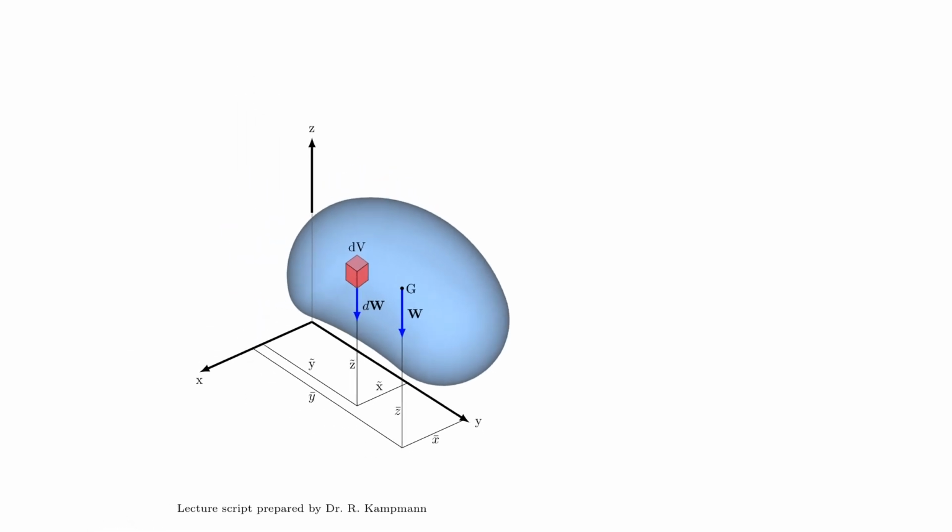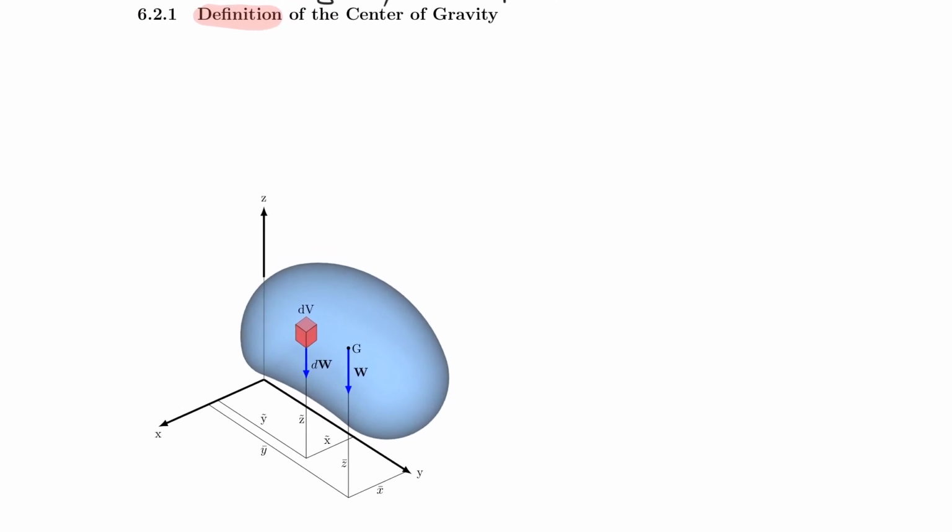So now the way the center of gravity is defined is that whatever point in space you choose, let's say you choose the origin of the coordinate system, there is a weight times a lever arm. So in the x direction, it would be W times x bar. And that would create the equivalent moment as each individual particle times its distance.